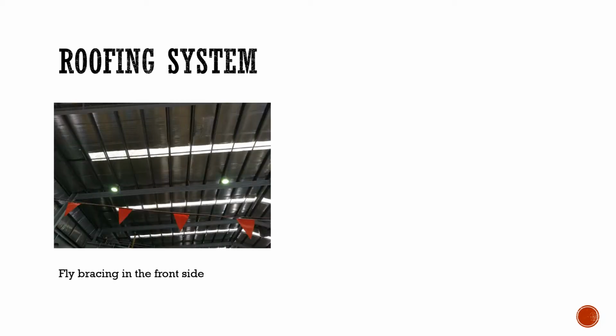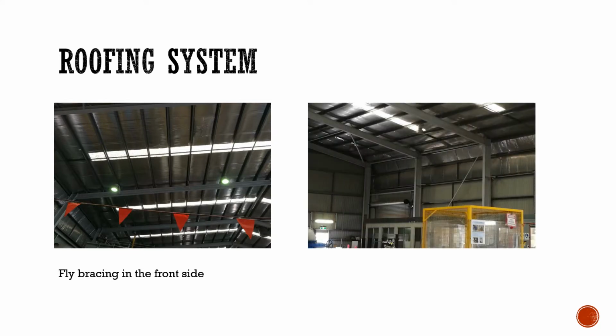And in the first picture, which is the flat bracing in the front side, purlins are placed at equal spacing, and roof cladding can be fastened on them. Flat bracing connects rafters and purlins as appears in picture 1, but they are not placed on the other side of the rafter shown in picture 2. This is a mistake of structural design because bracings should bear both directions of wind.